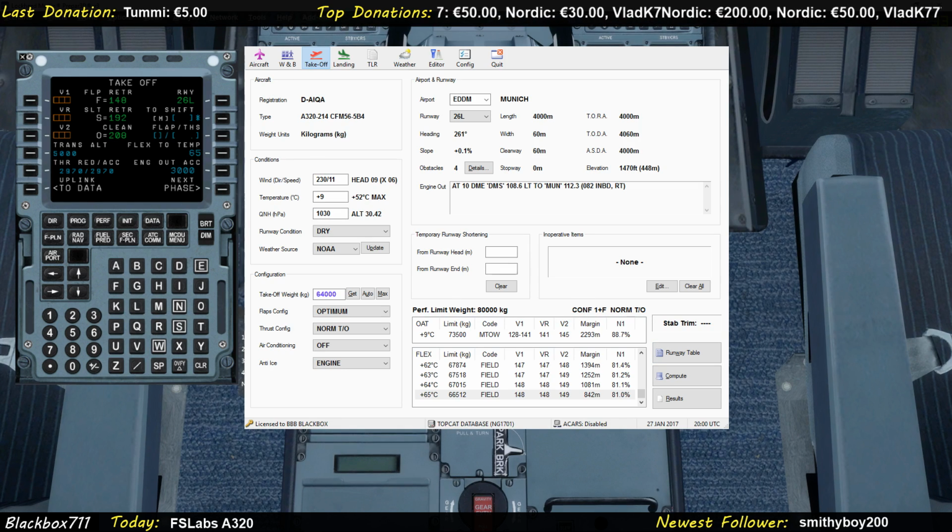So today, there could be a chance, since it's only scattered 1000, that we're going to enter clouds in the climb and temperatures below 10 degrees. And so we would have to use engine anti-ice. That's why we selected engine anti-ice, and that way we're on the safe side. Because engine anti-ice takes bleed air away from the engines for the anti-icing, meaning less thrust.